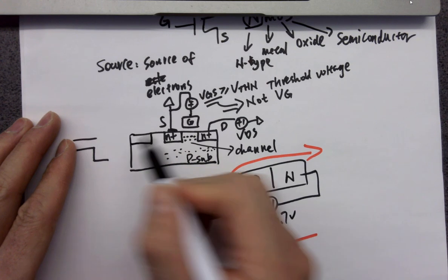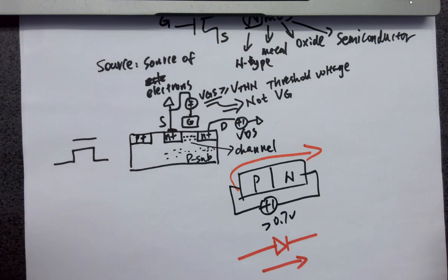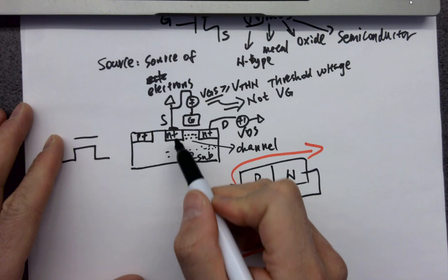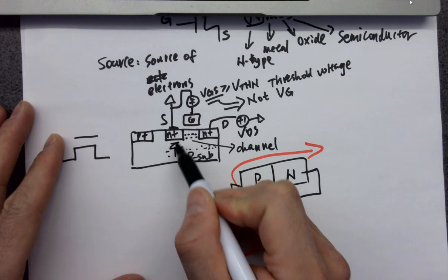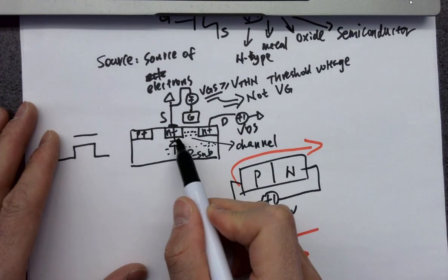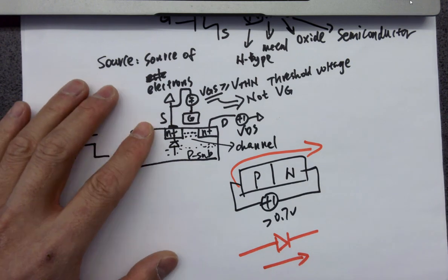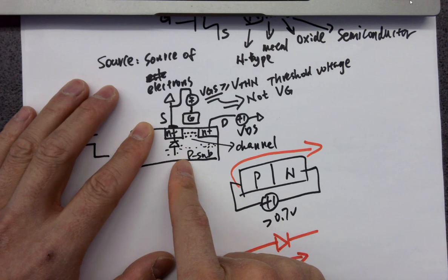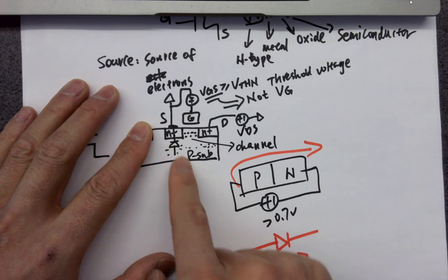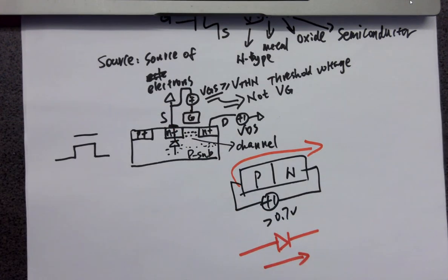for example, I have a little P tap over here. I'm going to explain why we have this one over here in a bit. If the little parasitic diode being formed over here is getting forward biased, what's going to happen? You can see there's a diode here, right? It's a PN junction. Just in case your substrate has a little voltage, for example, it's not 0 volts, like 0.7 volts or 1 volt, and this N node is grounded, what's going to happen? That's awful, right? Why? Think about it.